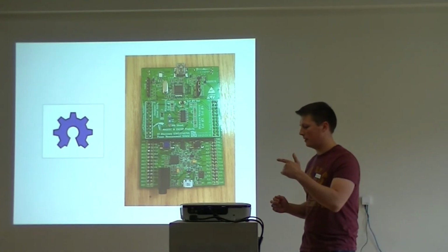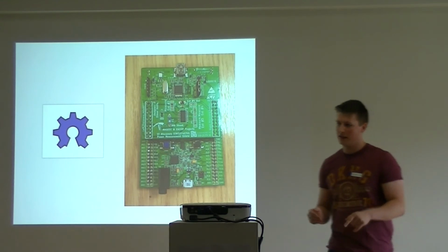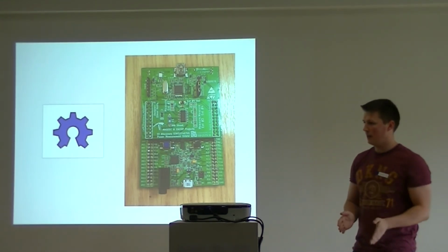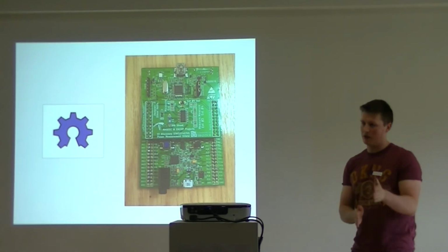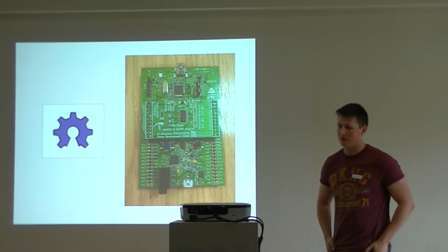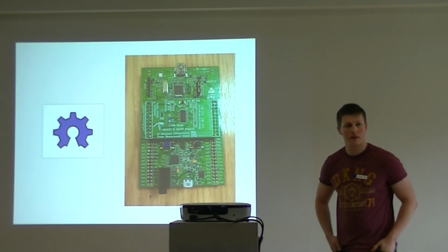So you trigger this pin, you see that in the trace, you can get GTKWave to say an event happened here, and then you can plot that on the power trace as well. You can correlate that spike back to your application. So you need to plant milestones in your code essentially.